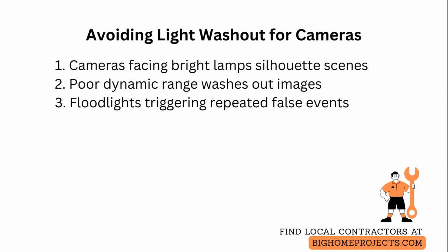A third frequent concern is motion-triggered floodlights activating too close to the camera and causing repeated false events. Resolve this by adjusting sensor zones and delays, relocating either the light or camera a few feet, or switching the light to a lower intensity or different trigger logic.